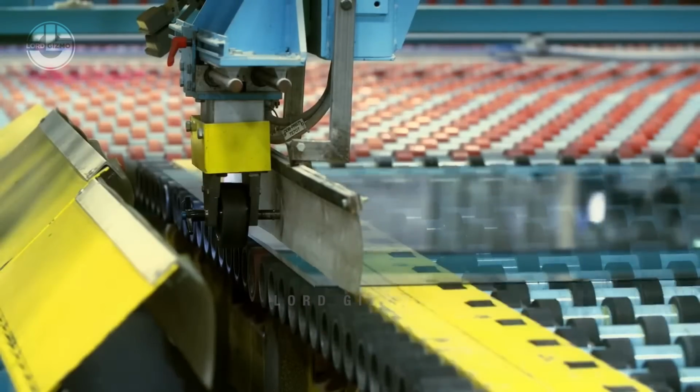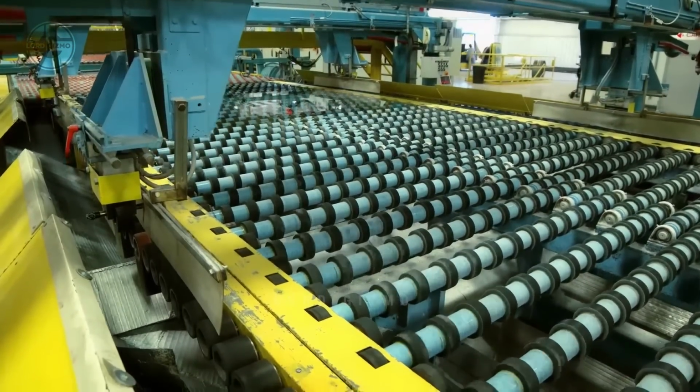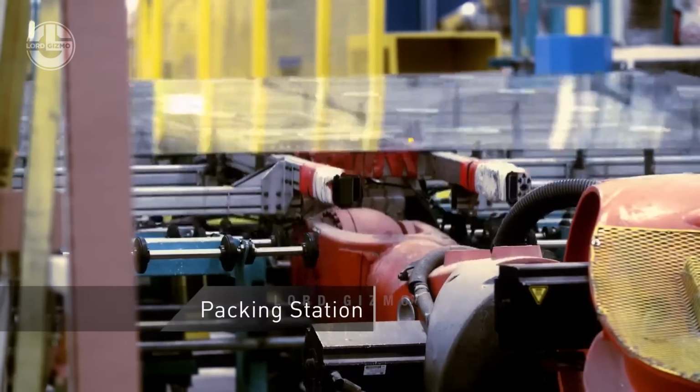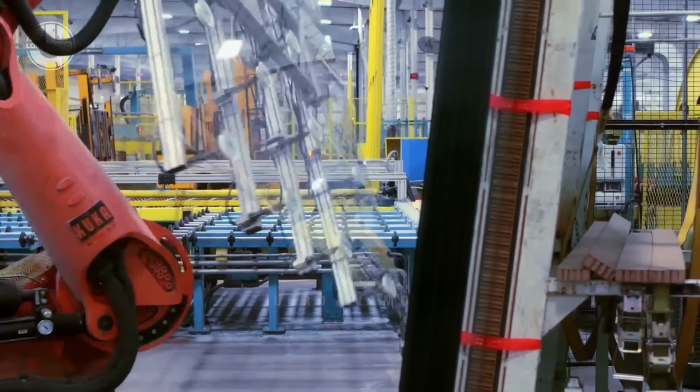If the glass's edge remains untrimmed anywhere, the laser technology detects this defect. The defective sheet is sent back to the batch house for recycling. Finally, the ready glass arrives at the packing station. Great care is taken to package, wrap, and label the orders.